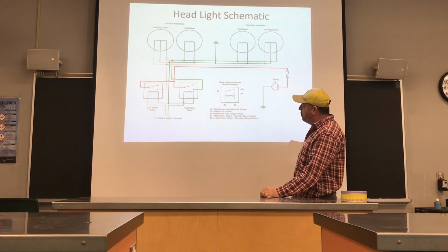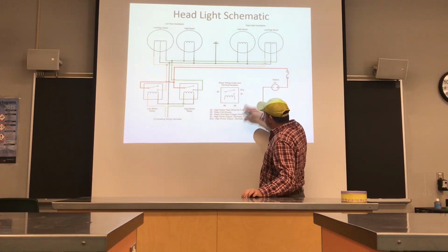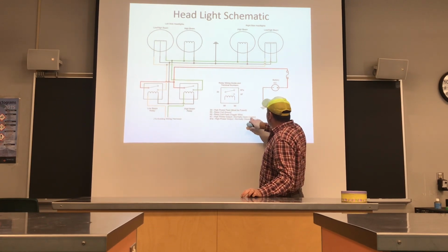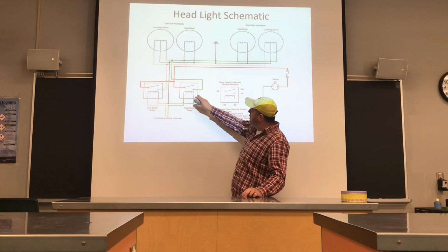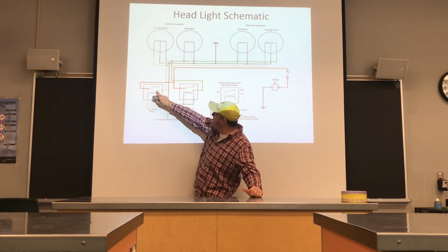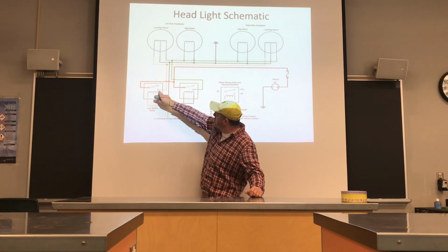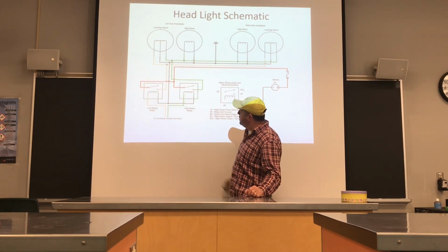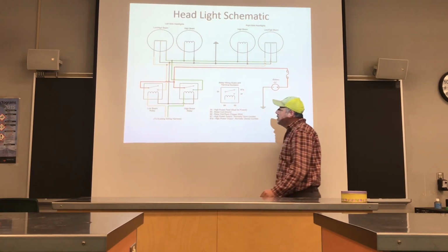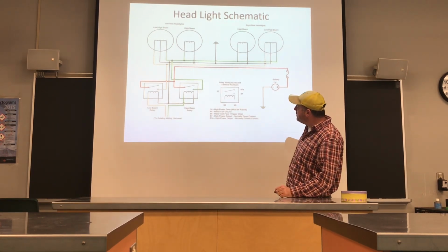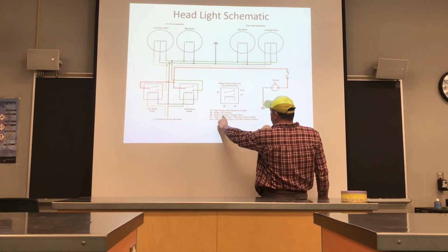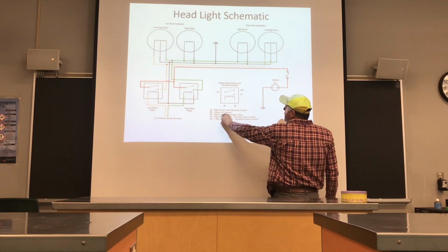It's just sitting there doing nothing. 87 is our high output, normally open contact, so this contact stays normally open, right? There's no contact here until we put control power to the coil, which is 86, I believe. Coil relay feed, or our trigger wire.